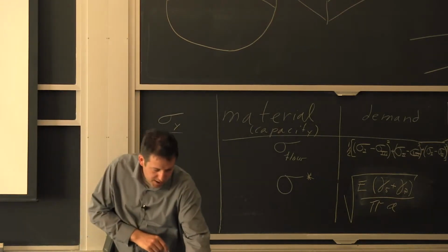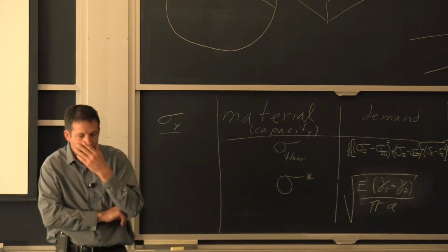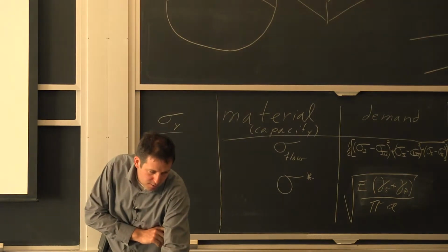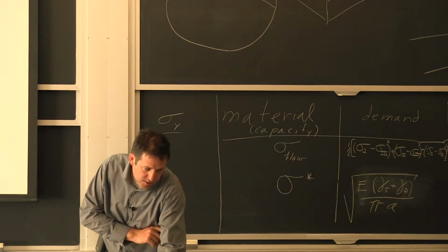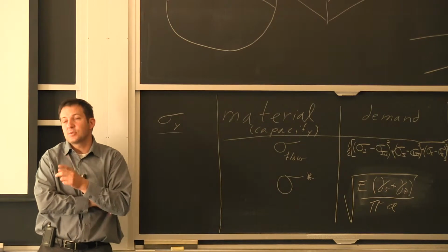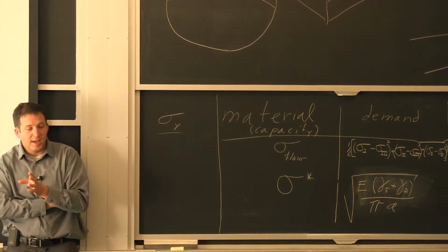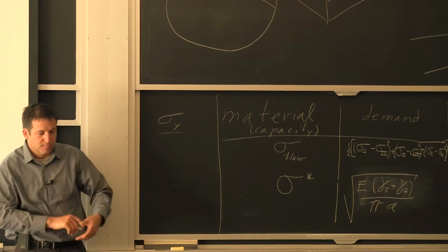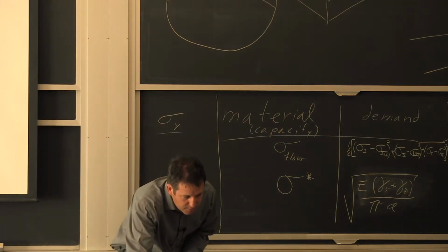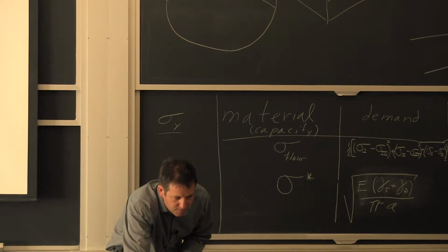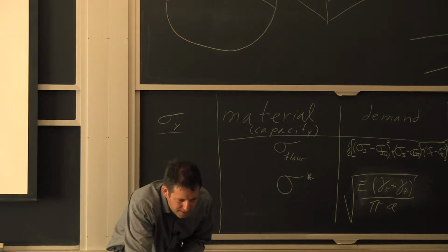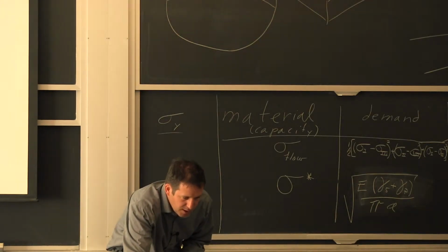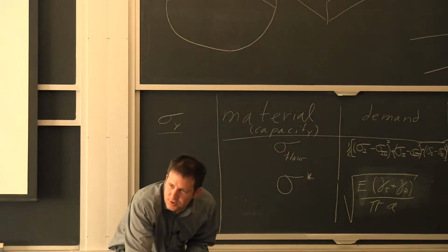That brings me to my example here with this turbine blade. We've done some stress analysis looking into the area here, and it had to be elastic, even though it's a stress riser. This is the highest stress you had in the blade. It was the leading edge. So this mounts into the rotor here, and what I'm showing is essentially some important contact points. We didn't have all of that figured out, but we were really trying to look at the effect of changing this radius here.